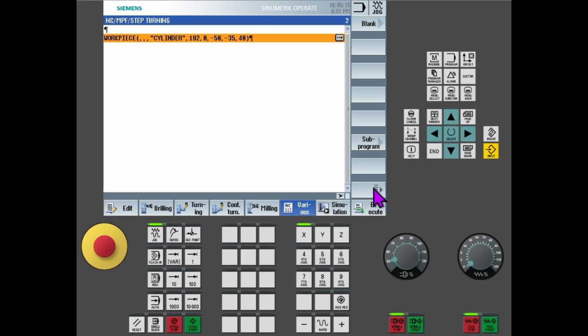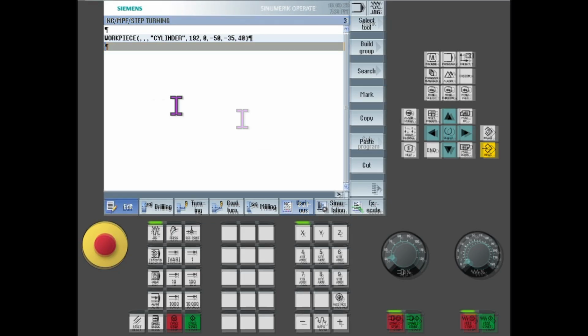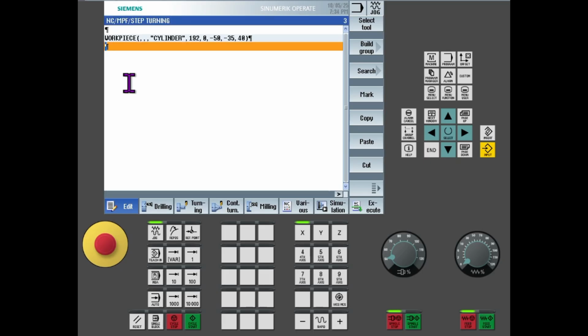After that, write down the pre-operation commands. Press input. I'm writing the pre-operation G codes and any commands. So the first command is G90, activation of absolute mode, then G71, activation of metric mode, then G95, feed in per revolution, then G64, continuous path control mode activation.